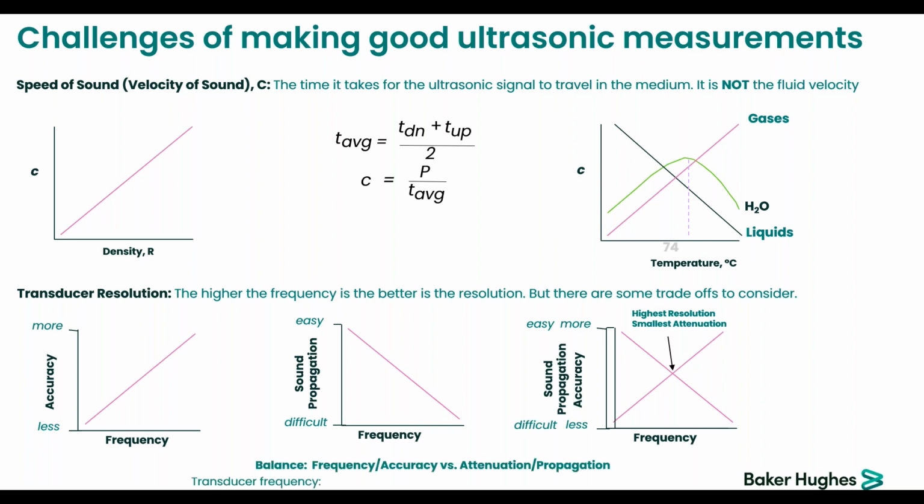So that's why within the spectrum of the applications, for liquid applications, for very small pipes, we will use up to 4 megahertz. Like if you have a half an inch, 3/4 of an inch, 1 or 2 inch, typically that will be this kind of 2 to 4 megahertz frequency. Then when the pipe becomes bigger, you decrease this frequency with liquid. So for very, very large pipes, you will go down to 0.5 megahertz or 500 kilohertz.